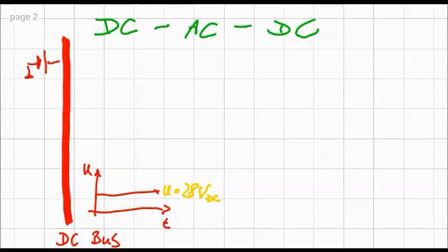Now, as we said in the last round, we can have different consumers here. We typically connect them through a circuit breaker. We have our consumer, close the circuit through the airframe, and that's it. Now, this battery has a bit of a disadvantage because it has so much energy available, and it's running down. But you know this from your notebooks, from flashlights, from your handphones.